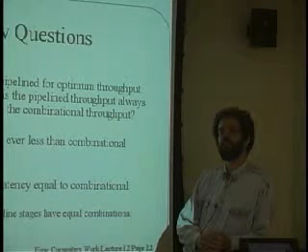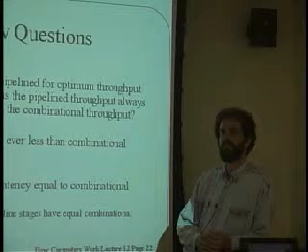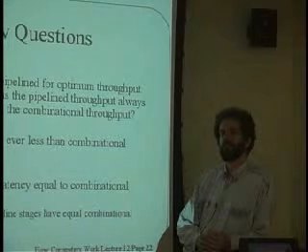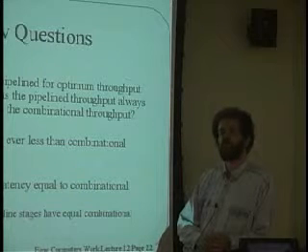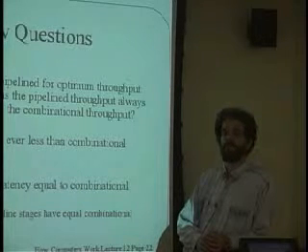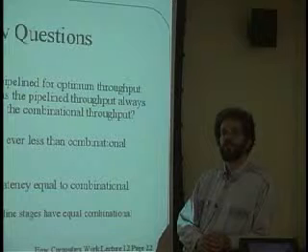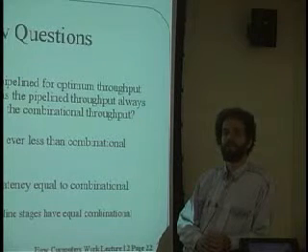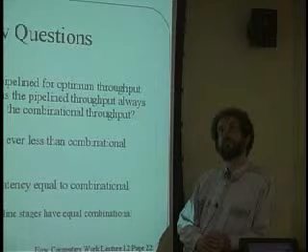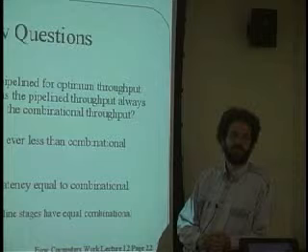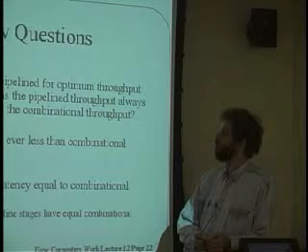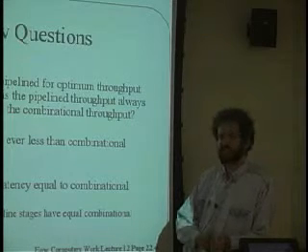What is the throughput of a non-pipeline circuit? 1 over the sum of all the latencies. Okay. What is the throughput of a pipeline circuit? Whatever the maximum. Okay. Can the sum of a bunch of numbers ever be less than the maximum of one of the numbers? No. That's the answer. Good. Knew you had it in you.